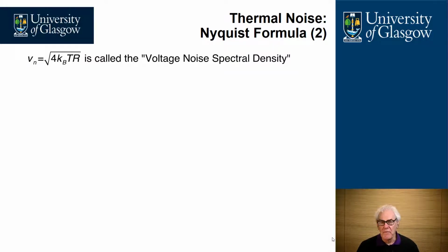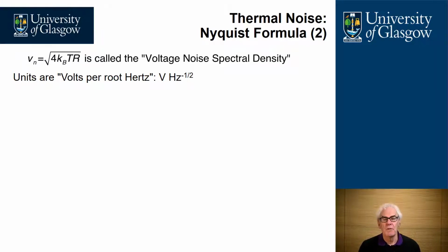We use the Nyquist formula. I know that many of you know Nyquist from the sampling theorem, but Nyquist was a communications engineer and he did a lot of studies into theoretical communications. Here we have the calculation for noise voltage, and it's the square root of 4 times the Boltzmann constant times the temperature times the resistance. From this equation, the units are always in volts per root hertz.